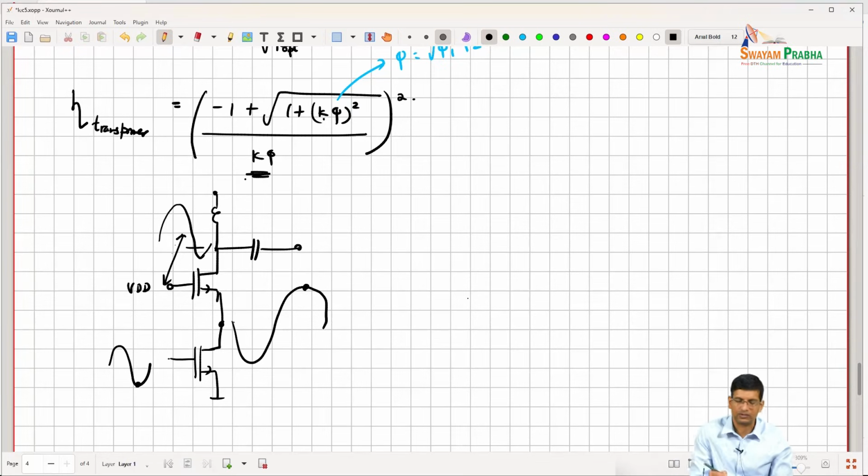In that case, you start getting limited by this over here, right? There are diodes here, so what you start getting limited by is the breakdown voltages of these diodes at the drain. The drain to bulk diode breakdown is basically what starts limiting you. So you can't keep saying that I'll pull more transistors in bulk CMOS at least.